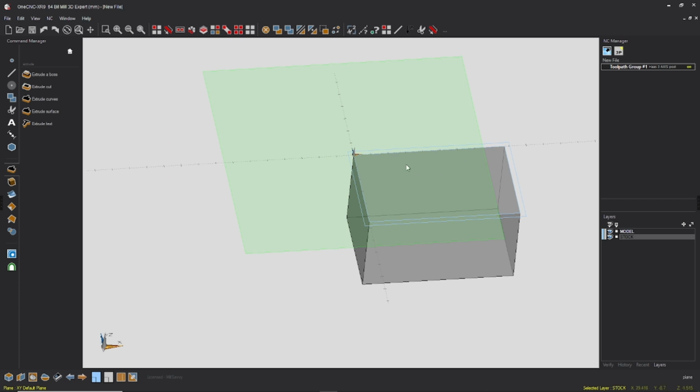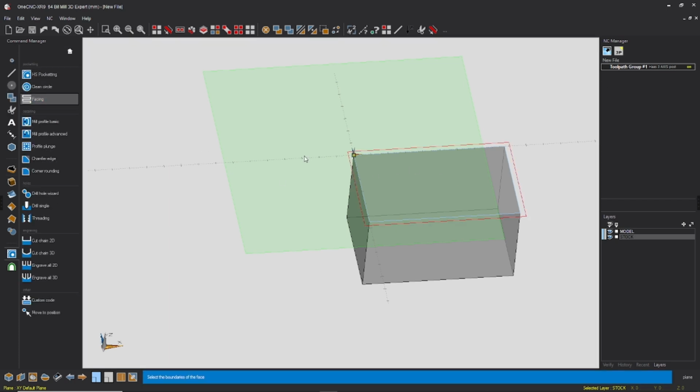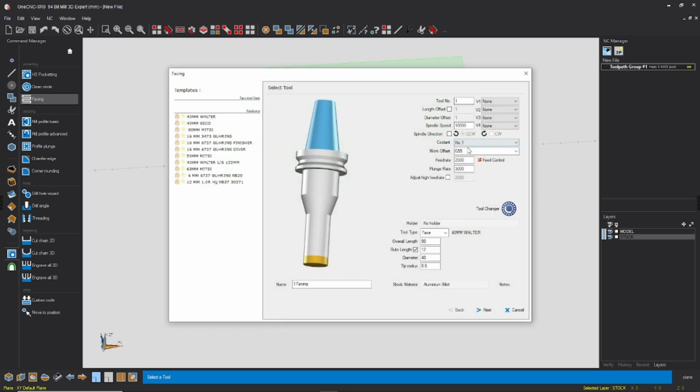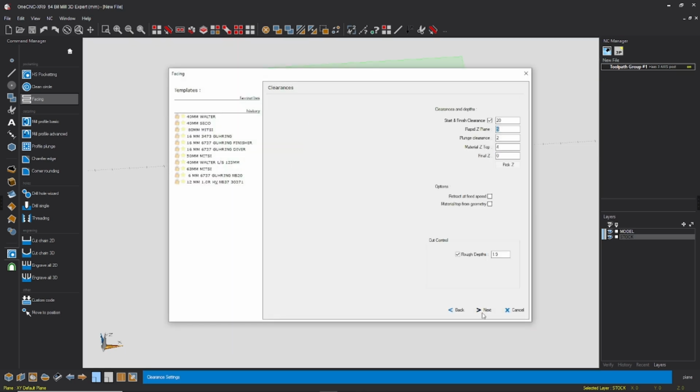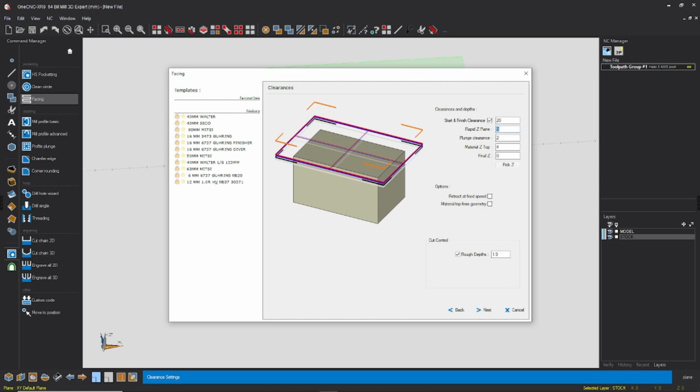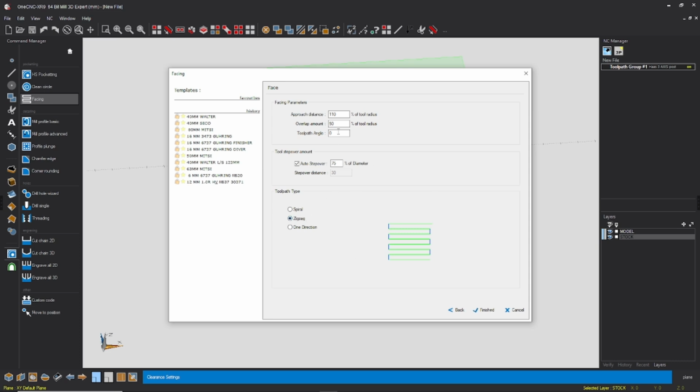So let's just quickly do a real bit of basic toolpath. Let's just quickly click on my stock. Don't worry about any of this at the moment. Speeds, feeds, depths, it's not really important at this point. Let's just say there's 5mm on top to come off. We're going to go down to Z0, and we're going to rough it at 2.4, leaving a 0.2 finish cut. We're going to zigzag 75 step over.